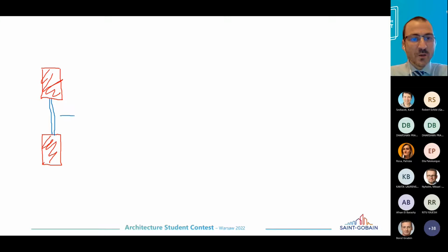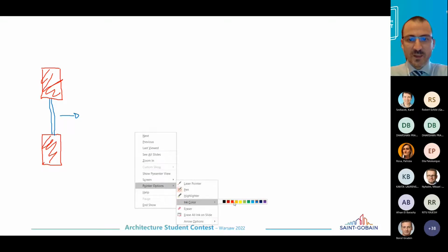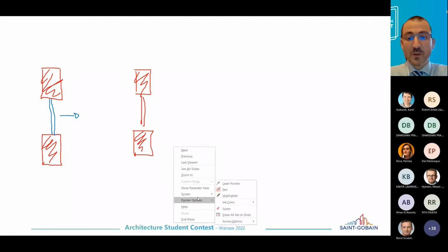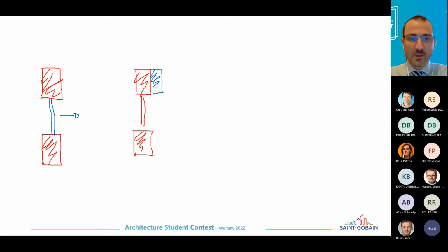And then from here you can go to the next variant, which is in the same approach. I have an existing building. Okay, this is my wall. I have here my windows, and then they decide, okay, let's do some insulation, and they put some kind of insulation here, let's say 10 centimeters of insulation, and they put also 10 centimeters of insulation here. And sometimes this is all they do, and in some other cases they will put also some insulation here, like this, more or less. Yeah?